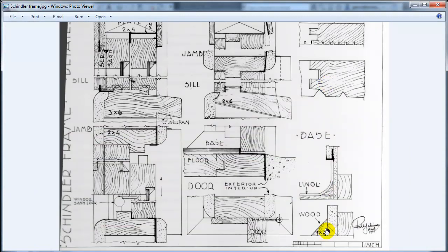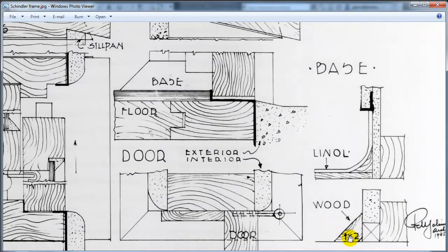Let's kind of talk about that. It's like 1 by 2, just kind of rolled at like 45 degrees, something like that. Okay, that piece right down here, that's a little piece of what I'll call stucco stop. What happens is you don't actually want to run your stucco or your plaster right on down to the floor. Just as the house moves and settles, you get cracking in it. So it's better actually to leave a gap or put a little piece of wood in there, just something so you're not running stucco down to a 90 degree perpendicular angle. You have a cracking problem later.